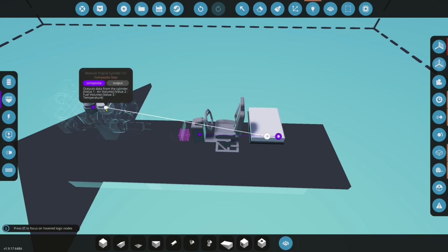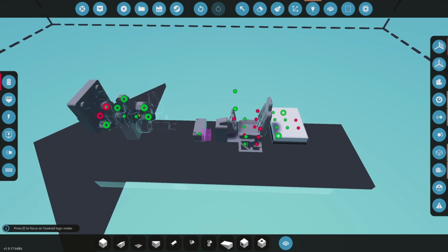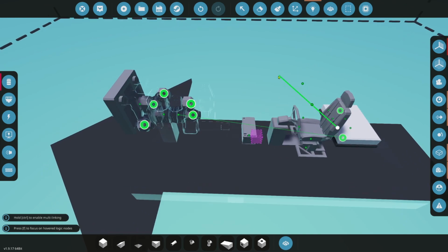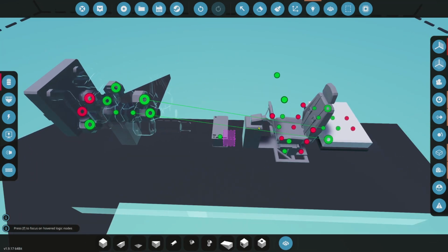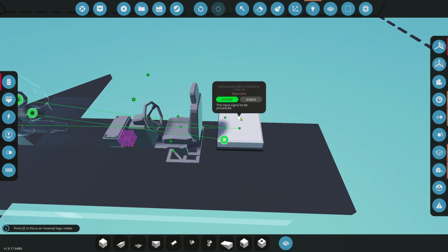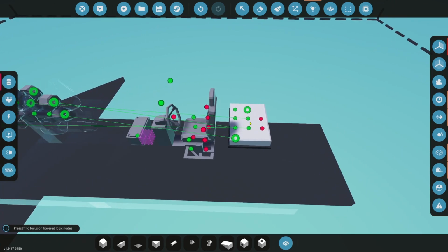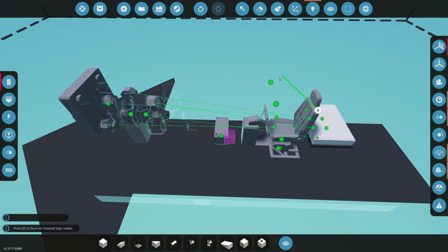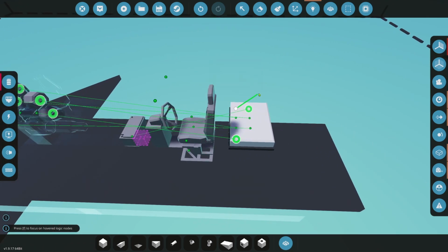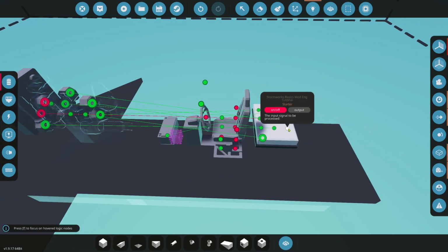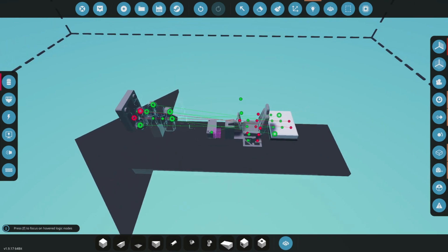So I plugged in the engine composite there. Let's plug in the rest of our nodes. We're going to take an RPS. It doesn't matter. You just need one of these off the crank. That's going to go to RPS. Next, we have the air manifold. That is going to plumb into our air manifold. We have the coolant pump that pumps into our belt-driven coolant pump. Alternator goes over to our alternator. The fuel manifold goes right here to our fuel manifold. The battery is going to plug right in there. The clutch goes right there to our clutch. We have the radiator fan, will go right there, and the starter goes right here. And we're pretty much all plugged in.